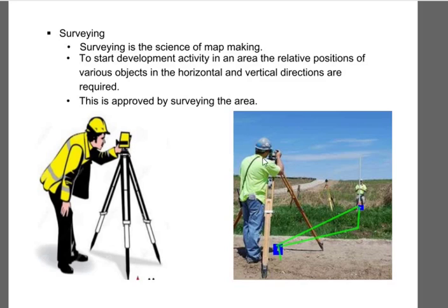So by using an instrument, for example, a total station or auto level, whatever instruments are used, this instrument directly gives the horizontal distance as well as the vertical distance. Now this instrument should be set at a particular standard height, and this is called a staff. By identifying the readings on this vertical staff, we will bisect the readings using the instrument. Again I'll mark this like this. We will identify the readings by doing calculations and find out the vertical distance. This process takes some time. By identifying this you will identify the vertical as well as horizontal distance by using this instrument.